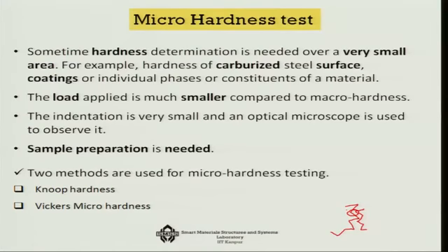So, in this kind of surface, you must give a special coating on the teeth of the gear. You give a special very thin coating layer, which is very hard, so as to save it from wear and tear. Now, this kind of very thin coating layer, you cannot really use the macro hardness tests for. You need a micro hardness test for doing it.